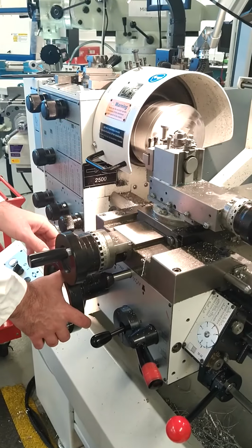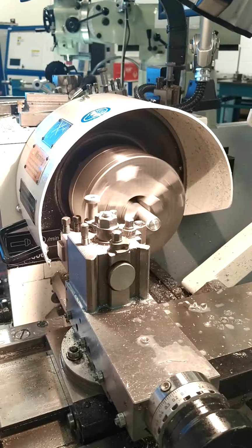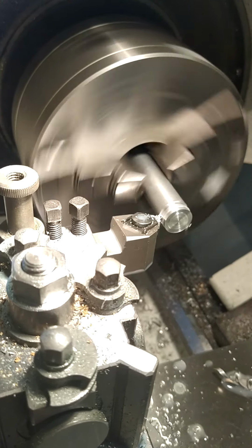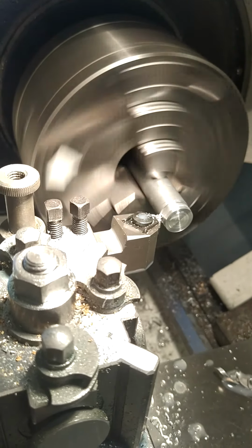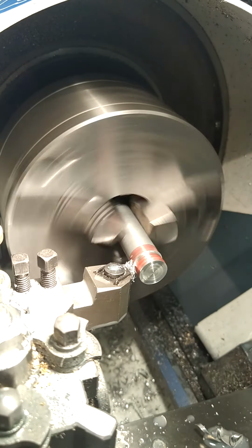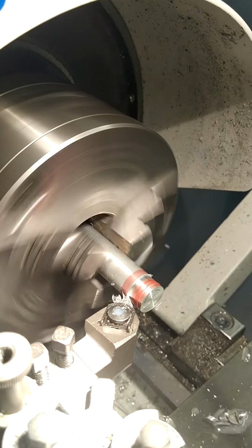That'll give you a very bad finish, as you can clearly see. What you want to do is a nice continuous feed to get a continuous chip coming off the work. If we don't have a continuous feed, we get a very bad finish, like we did here, from the jerking. So to use automatic feed, you push in the lever here, which causes us to go down the Z-axis. Then pulling up the automatic feed, we now have automatic feed traveling down the Z-axis. So you're automatically machining the Z-axis.